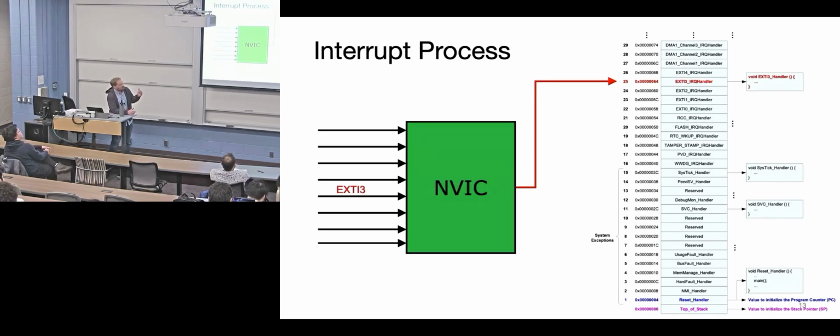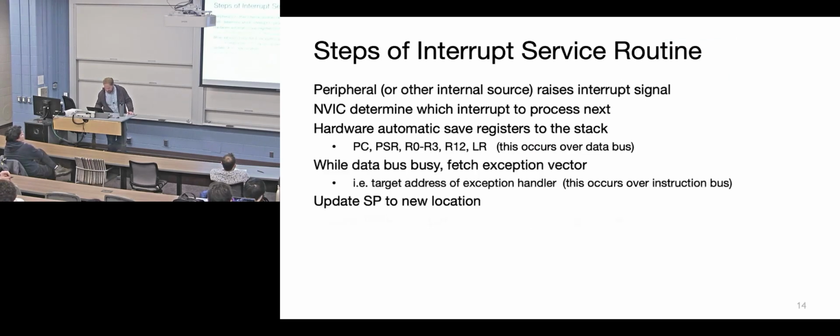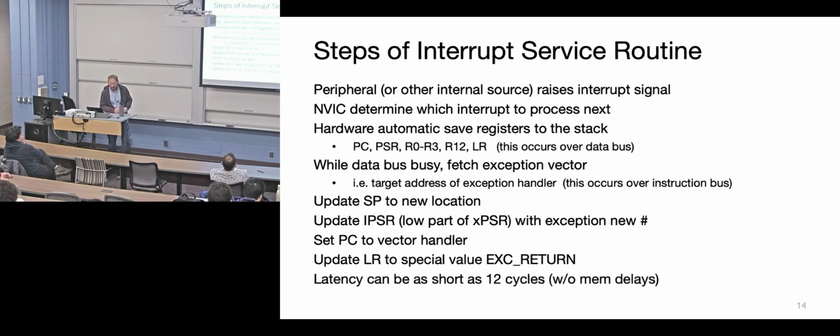So remember, maybe it's written here in a very wordy way. When an interrupt occurs, you have to preserve the state of the core. The whole idea is that program execution in main mode should not be aware of, or interrupted by, the interrupt. Code execution shouldn't be changed or corrupted or affected by the interrupt other than just waiting in time.